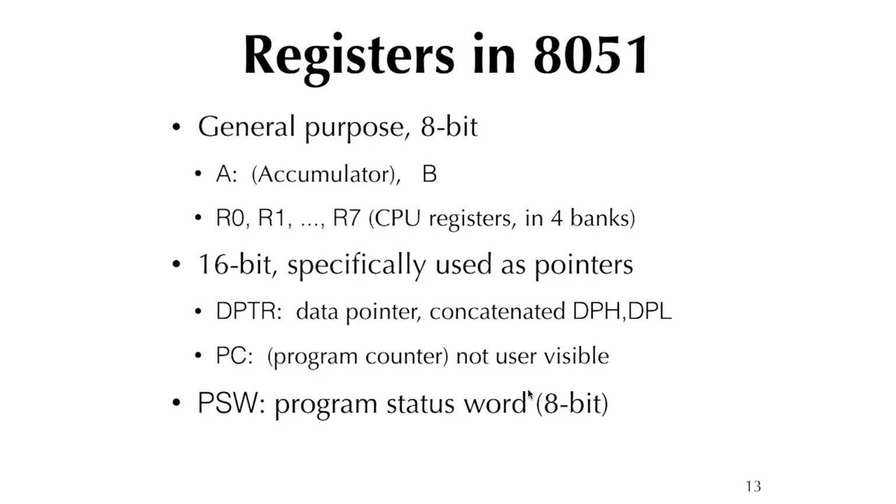There's something called PSW that stands for processor status word or program status word, depending on the terminology. But both start with P. So these are bits that are needed by the processor to support program execution. And if you want to know detail, you can read the data sheet, but we'll talk about a few of these bits over time. For now, you just think of these as control bits used by the processor.